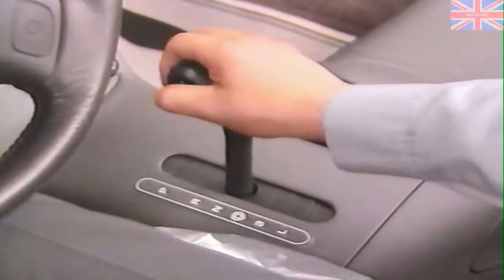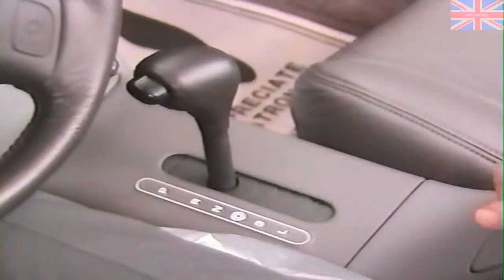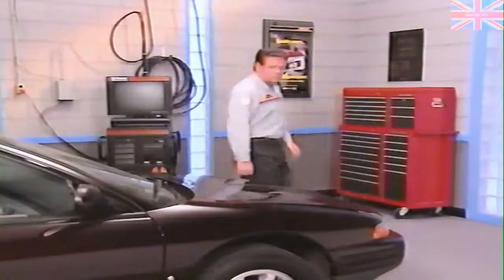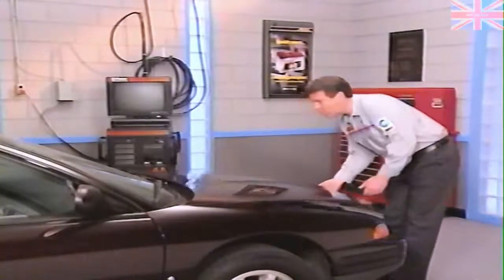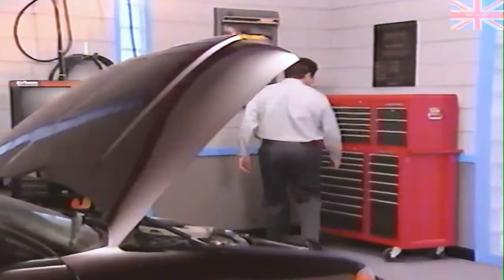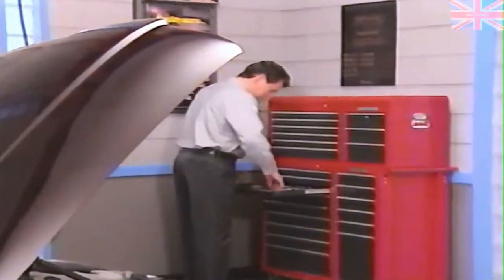Repeat the procedure with the transaxle in reverse. If noise or vibrations occur, worn engine and transaxle mounts are probable causes. If you have determined that the noise or vibration is definitely engine speed related, perform the engine accessories test to narrow down the possible trouble source.